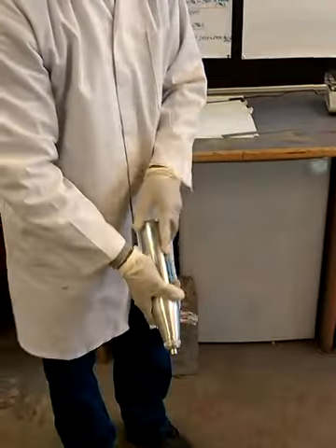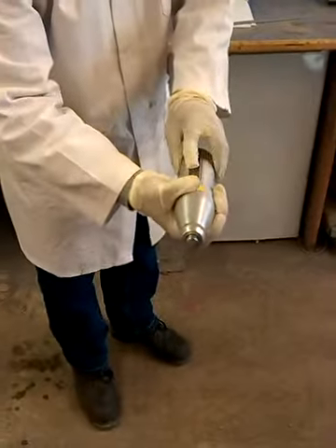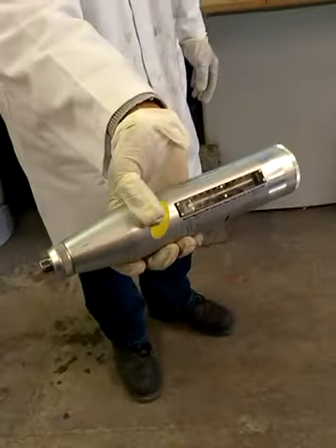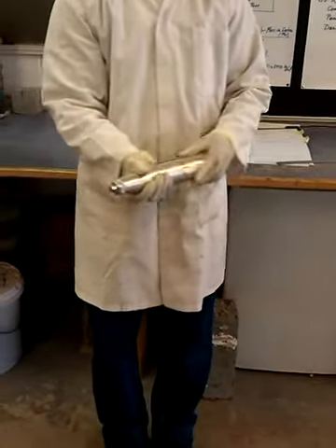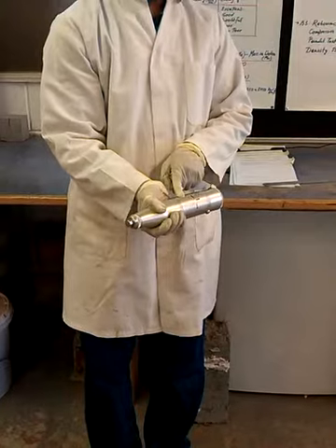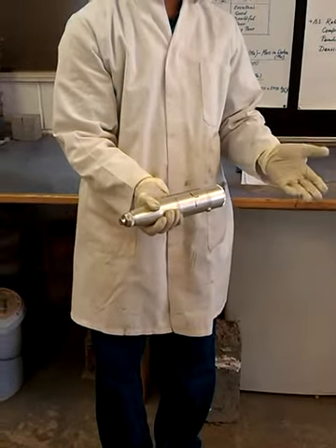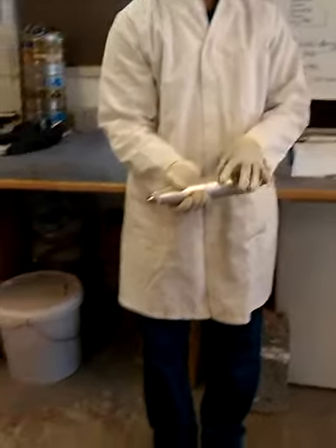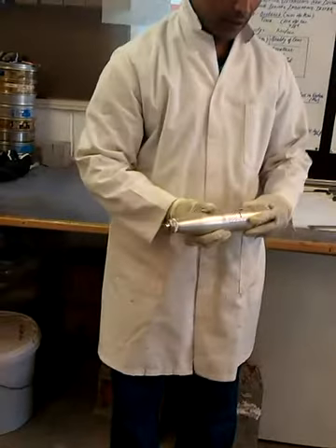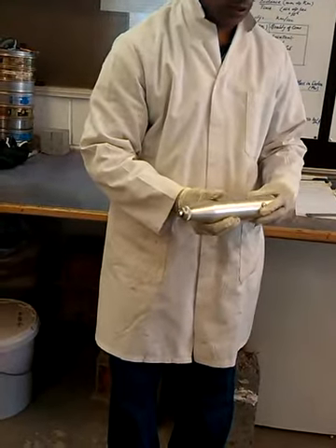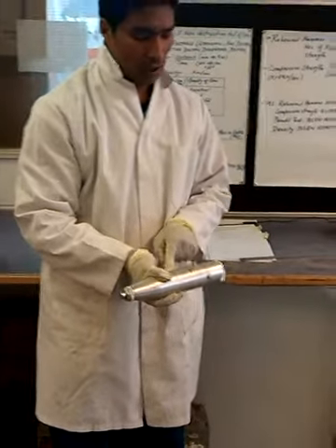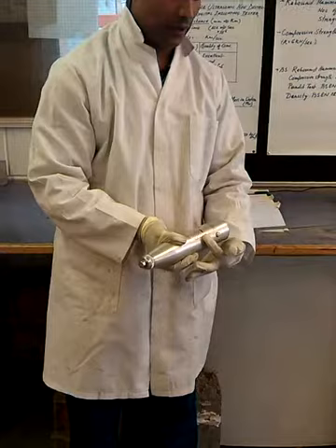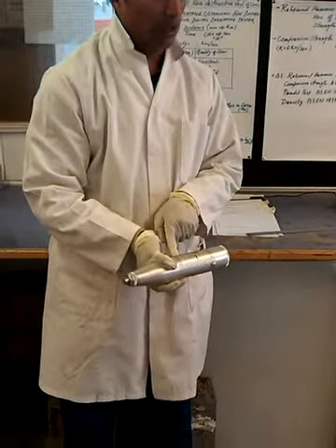For example, now from this one, how much you got is 30, 40. You get this number over here, 40. This is the rebound number from the surface of the concrete. Then, luckily we have got the graph in the hammer, right? Most of the hammers have it, but some of them don't have the chart. If you have that chart, what you can do is convert that rebound number to get the strength of the concrete. So you have your rebound number in the x-axis, and in y-axis you got the strength.